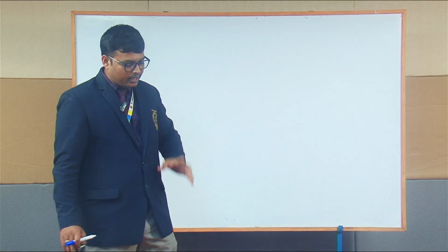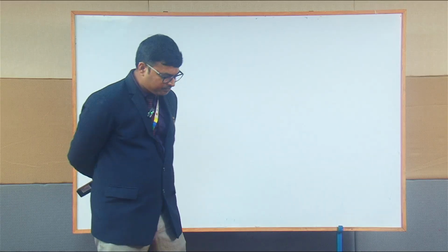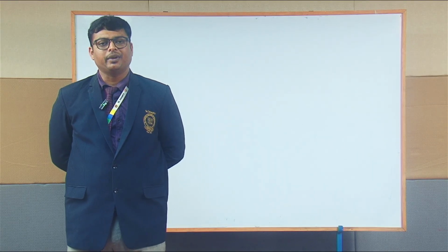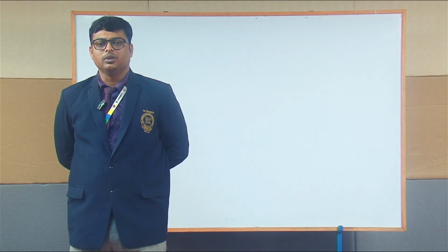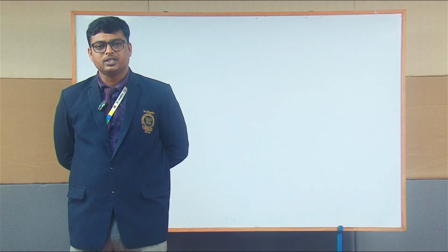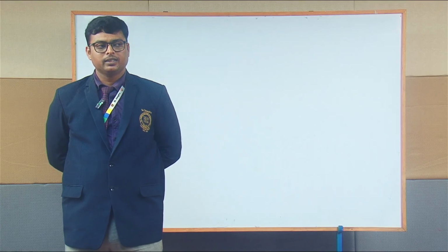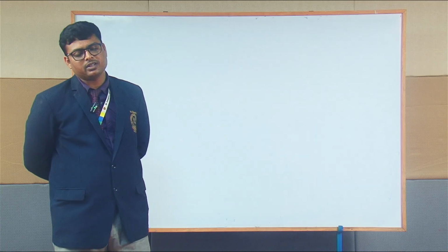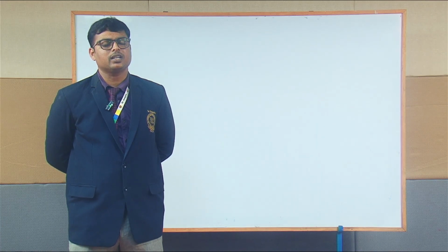And now coming to the end effector. So, what is an end effector? An end effector is a point or a tool where we make this robot customized for an application. Say for example, if I am working on a painting job, if I employ an ABB CRB 15000 robot for the painting job, then the painting tool which is put after the wrist will be considered the end effector. Say if it is a welding job I am going to pursue, then the welding tool will be considered so. So, the end effectors are customizable.